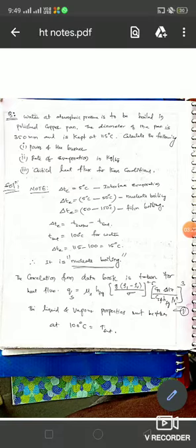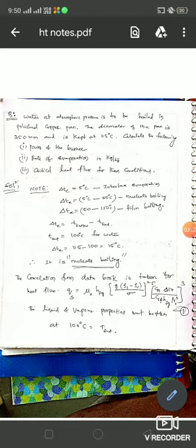If the pressure is given differently, say 3 bar, you need to go through the steam table and record the saturation temperature at the given pressure. Here, for 1 atmospheric pressure the saturation temperature is 100 degrees Celsius for water.